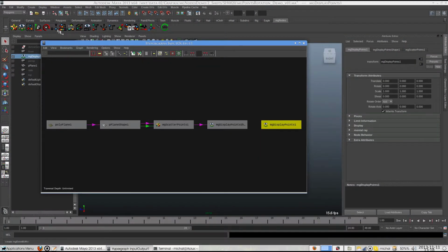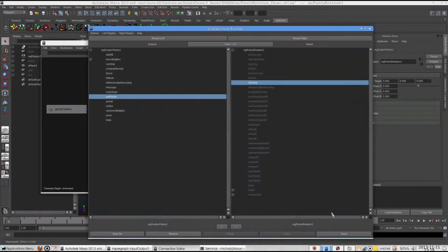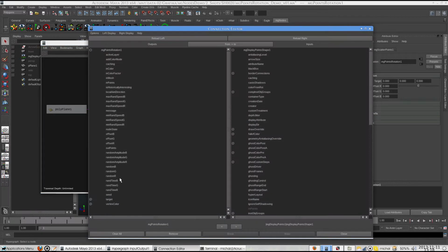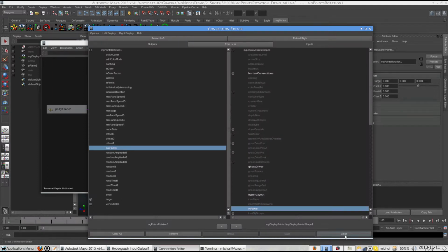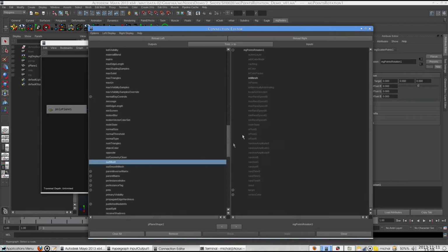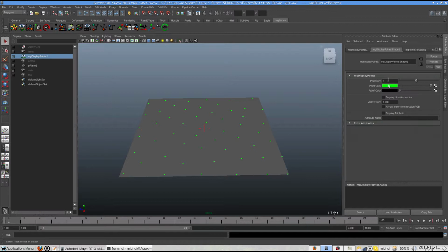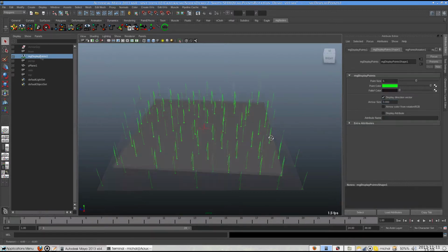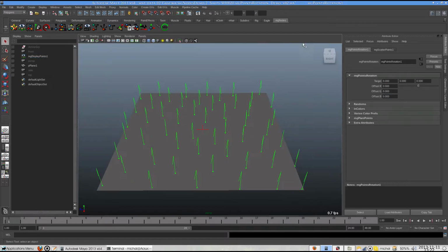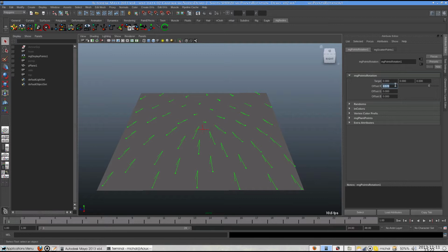mgPoints rotation node computes rotation for every point. This rotation is utilized by Maya instancer. Check appropriate option in mgDisplayPoints node to draw aim direction vector. Node computes rotation based on RGB color value. Red element defines lean, green defines circulation, and blue defines up vector.